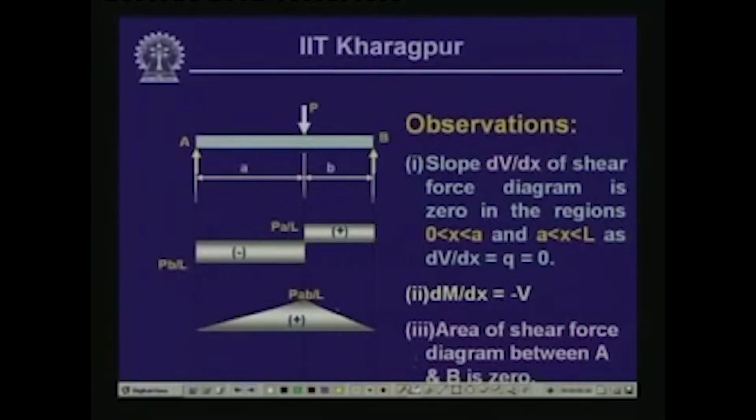Now, if you notice, the shear force and the bending moment diagram which we had plotted for a beam AB subjected to a concentrated load P at a distance of a, this of course is on a hinge support and this on a roller support, and since there are no horizontal forces, we said H is equal to 0, and we have these two vertical supports, and correspondingly we have this as our shear force diagram, and this is our bending moment diagram.